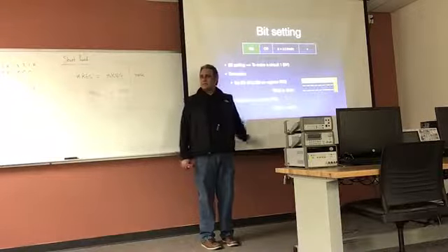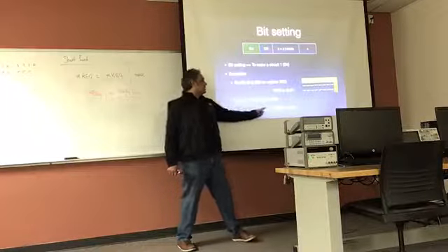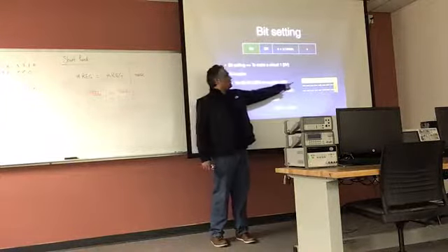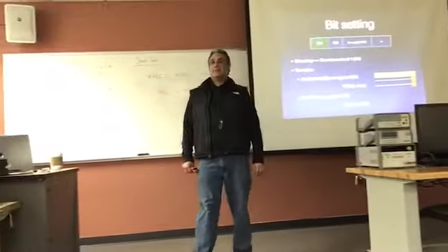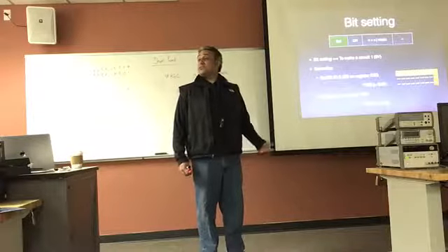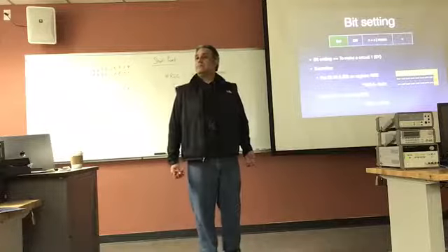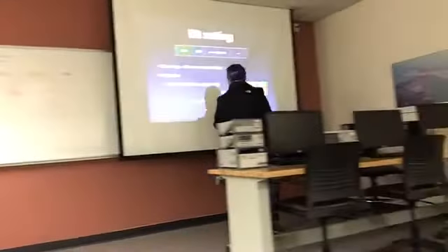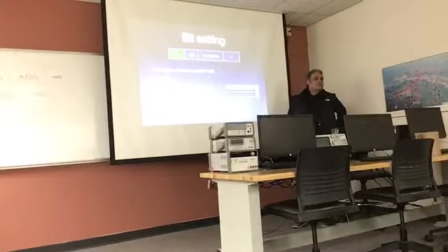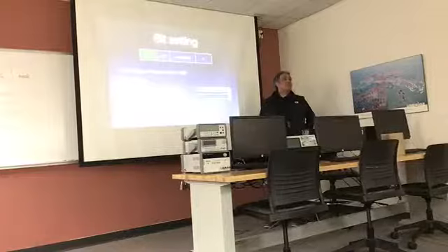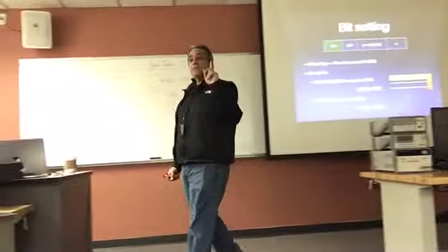You see that? Here is the example on bit 1. The only thing I did is that the shape remains the same, and I took a look at where is my positive mask, and I just simply plug and played it. Right? What is the shape of the instruction to set bit 5? Okay, good. Reg or equals hex 20. See that? We look like geniuses now. Isn't it? It's a very simple idea.